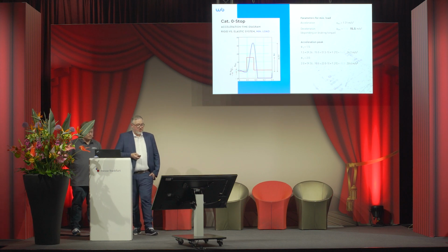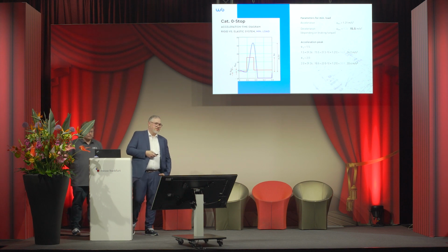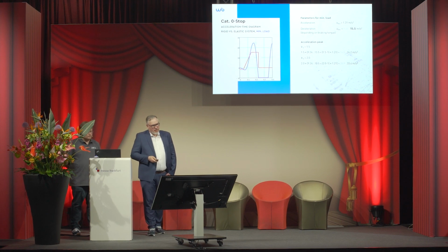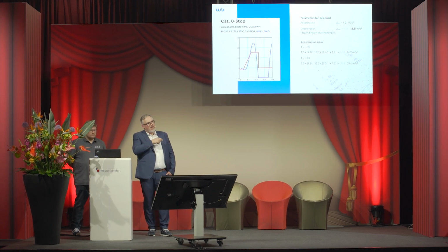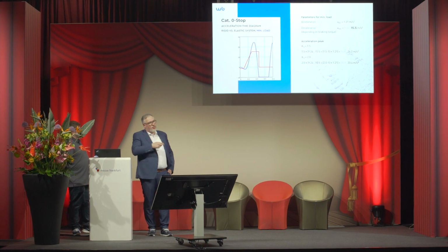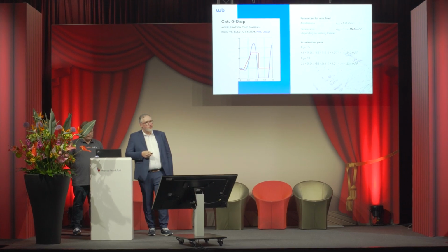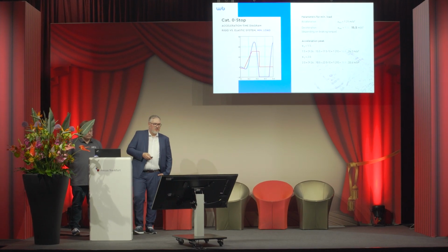And in the min load configuration, same factors applied again. You would have something between 24 and, worst case, 33.4 meter per second square deceleration rate. In our table, we specified this 24.2. Why? Because from our experience, also the studies we've seen, of course, the brake torque does not apply immediately. So if you simulate it correctly with an increasing braking torque where the brakes are closing, then the simulation comes to this level, which is 24.2 in this consideration. That is then the value that we would specify in the end user table.